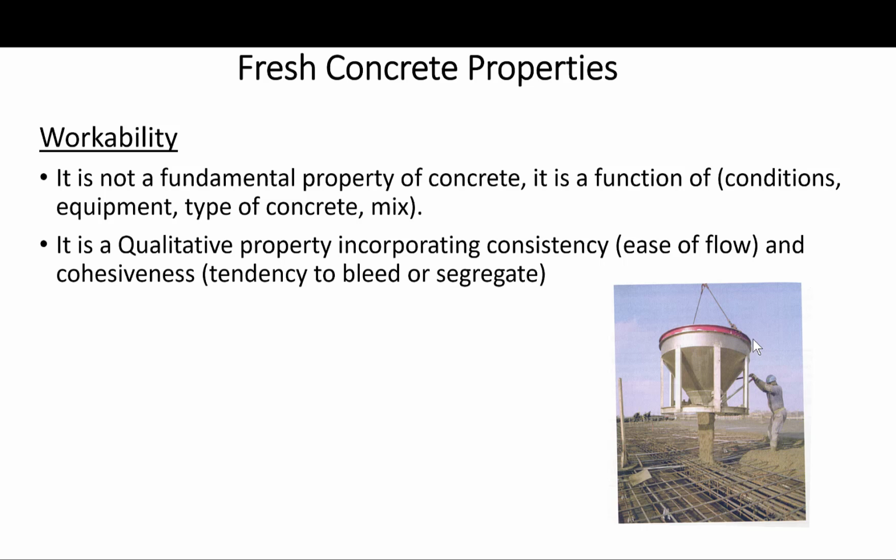But we have to remember about workability. It is not a fundamental property of concrete. It is basically a function of conditions, equipment, type of concrete, the mix itself. So it's not a fundamental property of concrete. It is a qualitative property incorporating consistency, which is the ease of flow, and cohesiveness, which is the tendency to bleed or segregate. So that's basically how you view workability.